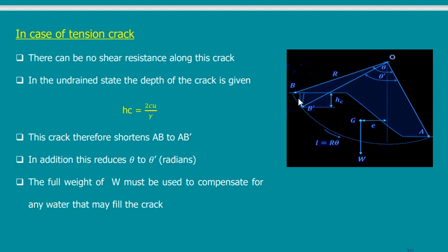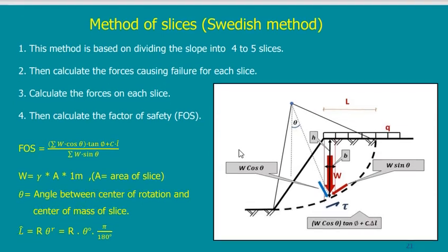So I don't need this friction. In this case, if I have a tension crack, then I should calculate the length only up to the depth of the tension crack. I should not go to the top of the surface of the soil.